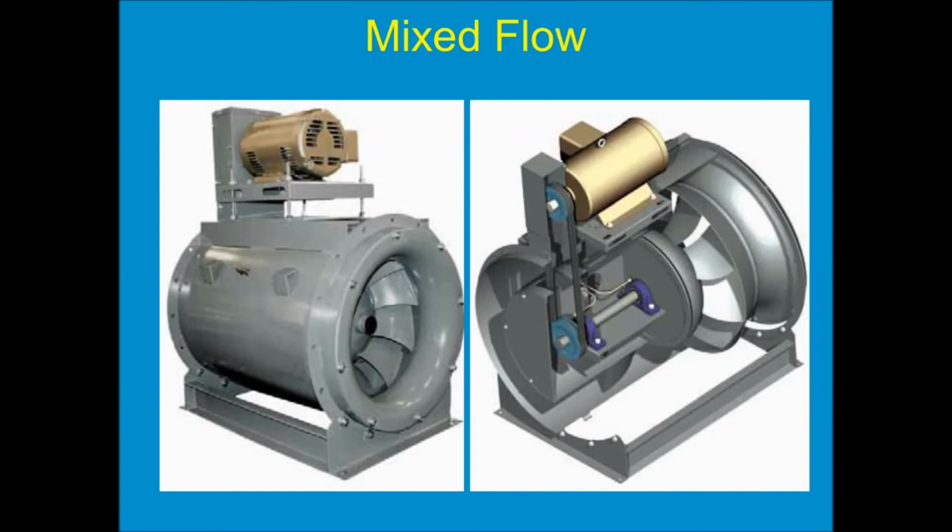Here's an image of a mixed flow type fan. It's a pretty heavy duty construction, so we would not really want to use this if we're only moving, say, 500 CFM inline. It would be overkill for that. But anything over, say, 1,000 CFM up to over 100,000 CFM against medium and even high pressure, up to 8 or 9 inches of pressure, this mixed flow fan is a great choice.